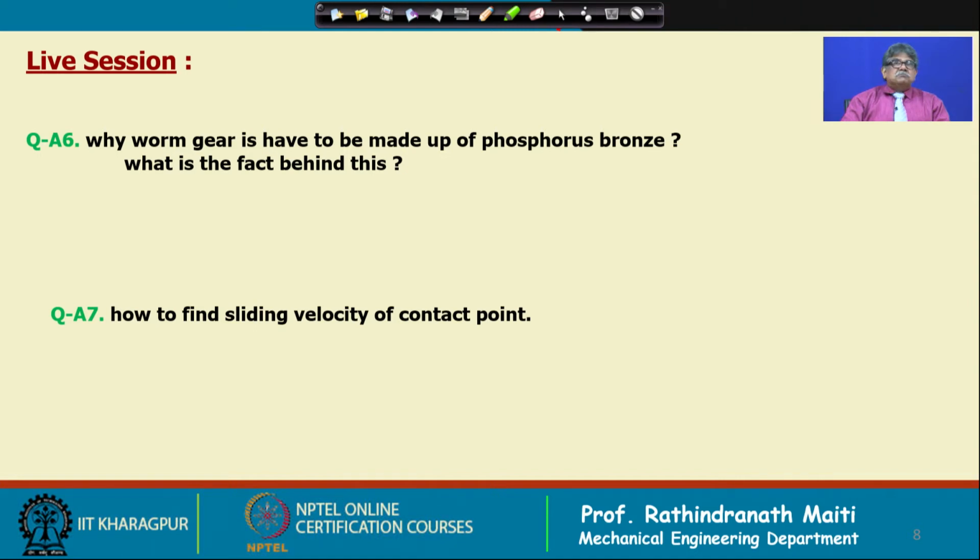Okay. So, in that way you can go for, say, steel, but then the losses will be more, though the size may be small. So, you have to compromise with that. Using phosphorus bronze you will gain ultimately, because your running loss will be less. It might be phosphorus bronze or some other material which has less strength. I would say that this is one point.